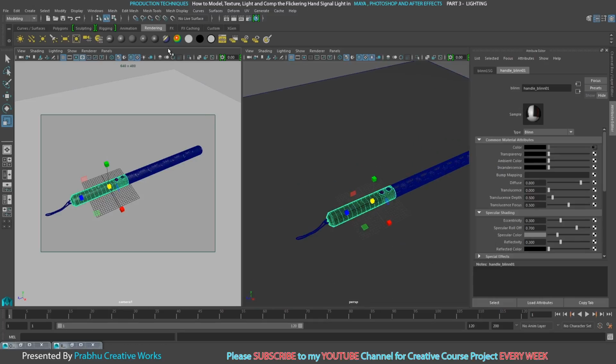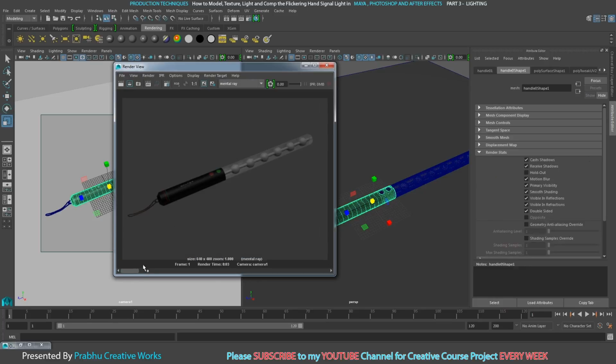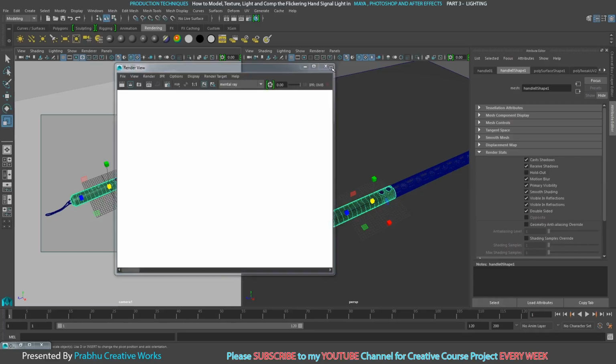Now select the scene, open the render view, click this one to keep the image, and click render again. So now you see it has lost a lot of specular highlights. Okay, now we want to give some reflection to this surface.